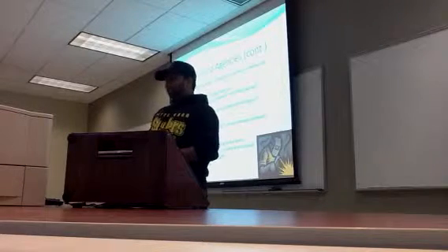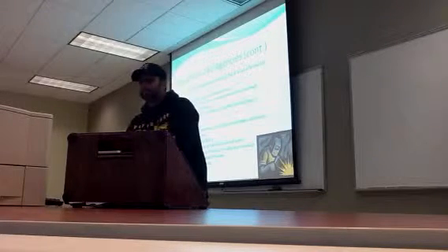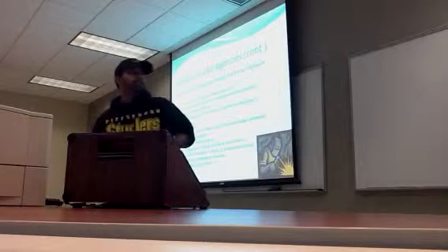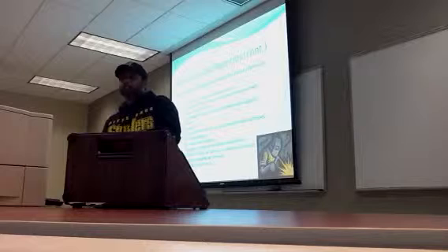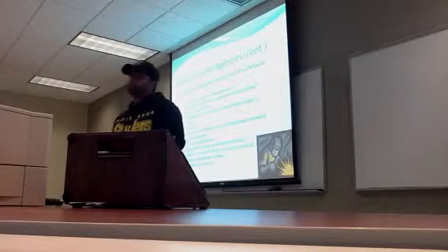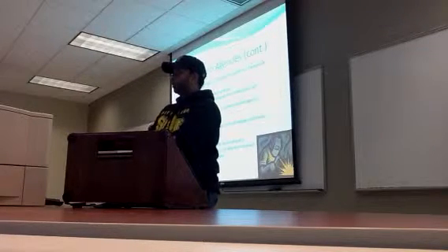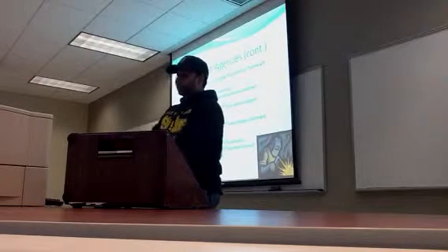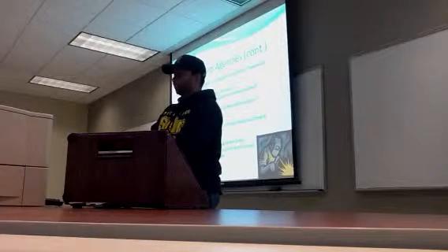And then there's process safety information, where the employers have to research the material, process hazard analysis, and operating procedures have to be listed for the employees. They have to know what the startup and shutdown procedures are, and also if there's an emergency, how to go about it. And contractors, they're also covered. They have to be trained by the employer. And pre-startup safety review, which has to be done before a plant is started up.